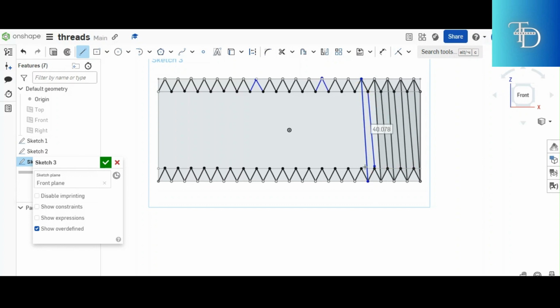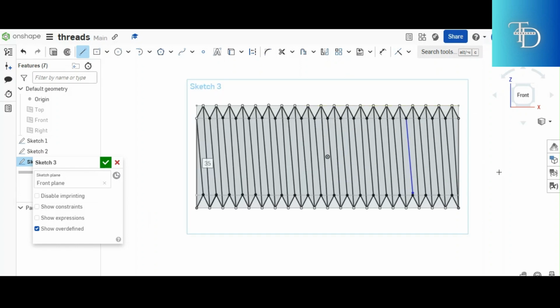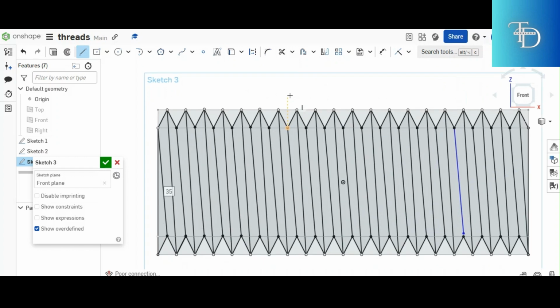So everything is starting to be clear right now as I'm completing this thing. It's starting to make sense. It's starting to look like a thread. You do the very same thing all the way up to the end. And then after completing that, ladies and gentlemen, congratulations. You've completed drawing what? A V thread, an external right hand V thread. This is how a V thread looks like. Something like this. Every time when you are required to construct a V thread, you construct something like this. An external V thread, it is something like this. A right hand, it's this direction.